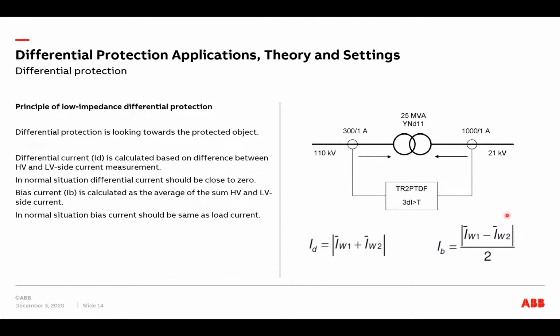So let's have a look at the basic principle of the differential protection. As I mentioned, the basic principle here is that we are calculating the differential current. So what flows into the power transformer should also flow out.